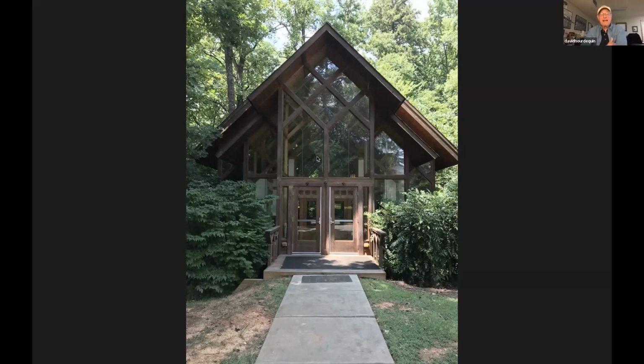This truss is so inherently stiff, it was incredible. And usually when they put inset glass, Josh could probably speak to this better than I can, but when you inset glass like this, I'm pretty sure it was all really heavy plate or safety glass. And there is some tolerance built around the frame. In other words, the glass doesn't fit perfectly at the timber. It's probably an 1/8 or 3/16, maybe even a 1/4 of an inch shy in each direction, and little moldings hold it in place that are caulked around the glass.